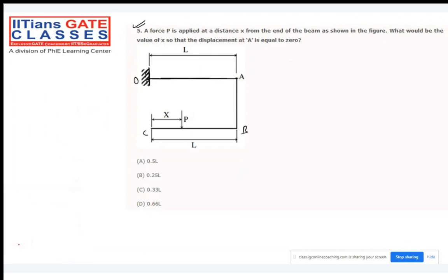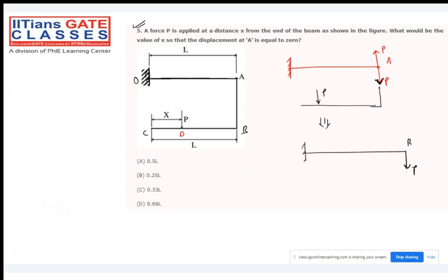See, try to shift the loading condition from point D to point A, and somebody told you how to shift the load: apply two loads which are equal in magnitude and opposite in direction, right? And there is a kind of P coming over here. So this P will create some kind of load. What is the equivalent diagram? The equivalent diagram will have one P coming over here at point A, one P coming over here, and this P will create the moment.